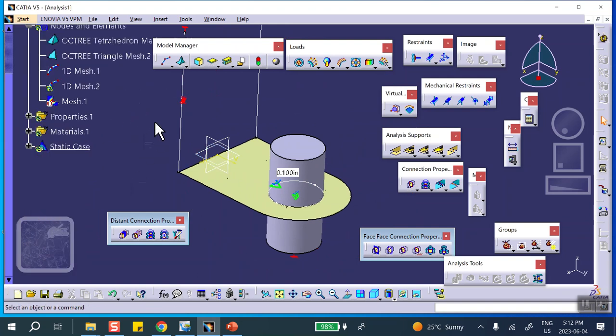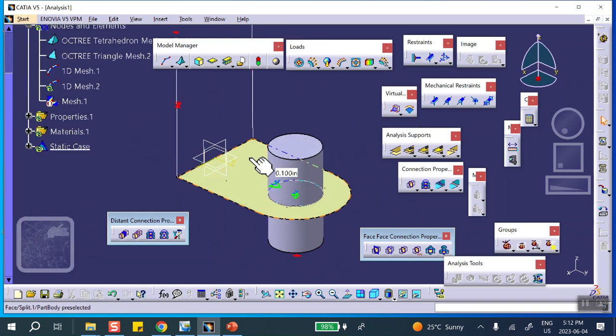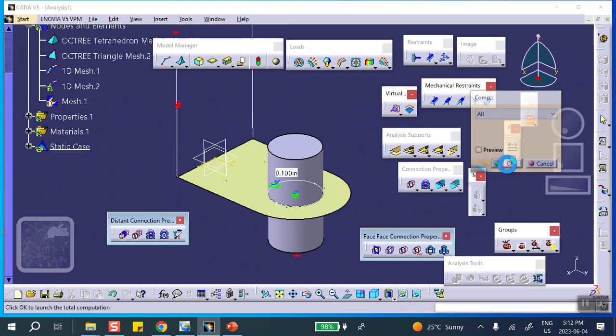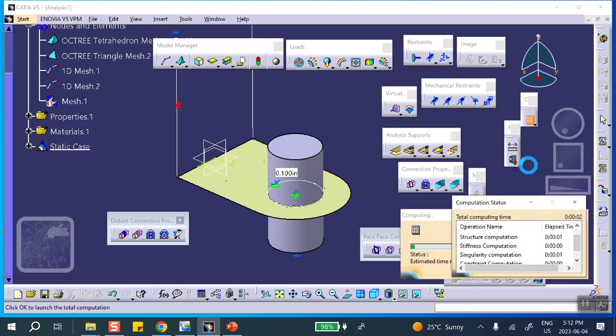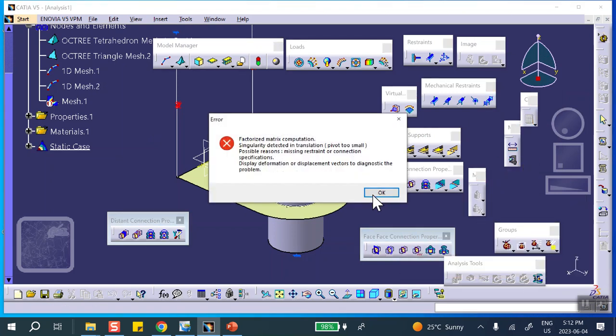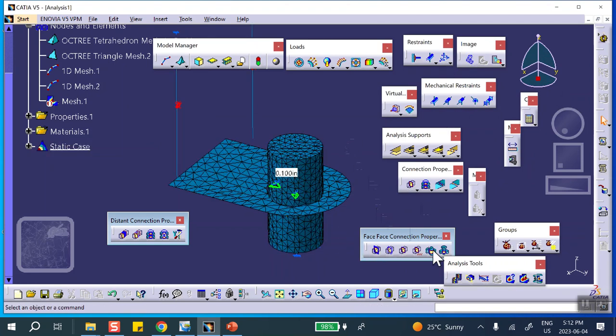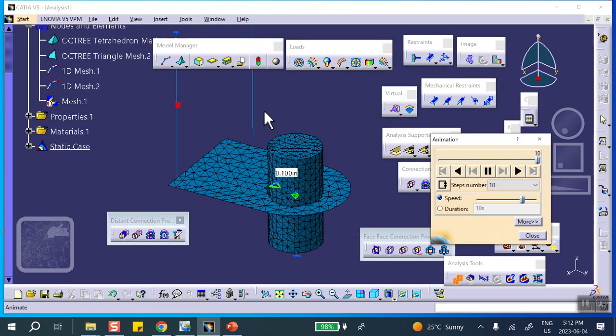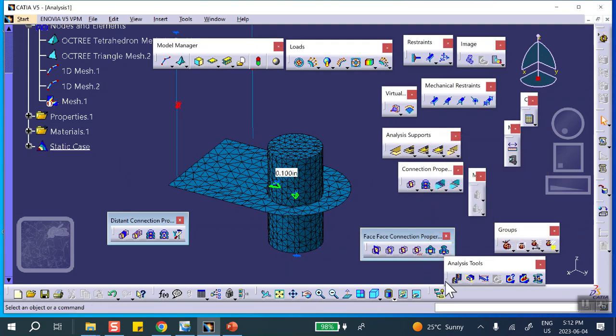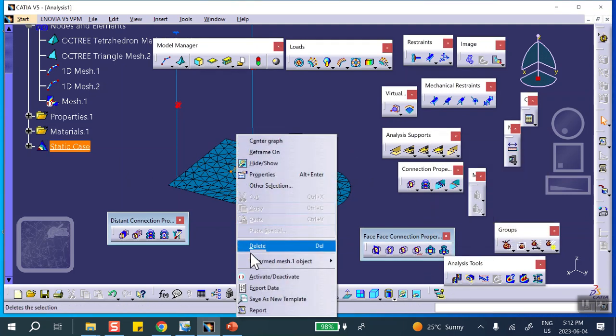Now, if we run this thing, it's going to fall apart because these guys have no idea the other fellow exists. Okay, so let's try it, run it, and you see that actually it goes nuts, moves as a rigid body. If you look at the deformation, for example, you can see that nothing is connected to anything else. All right, good. So deactivate this.